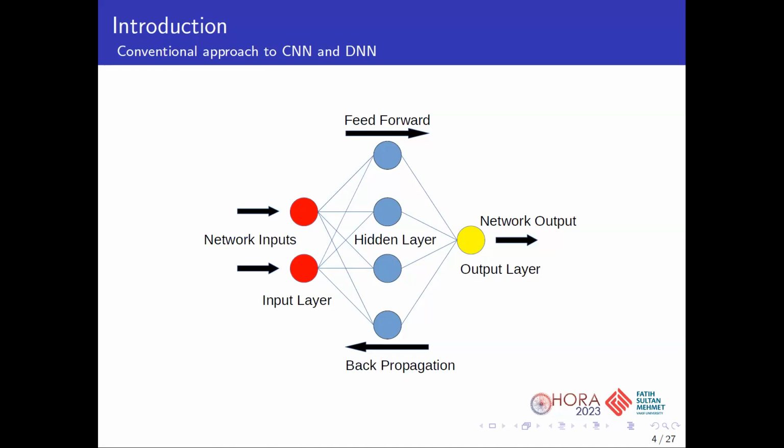Consequently, scholarly investigations have provided evidence that accurate classification can be achieved by utilizing 1 or 2 bit quantization for both the weights and activation functions. So incorporating low precision arithmetic and a compact memory footprint presents an excellent prospect for FPGAs to elevate speed and energy efficiency.